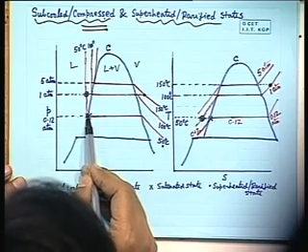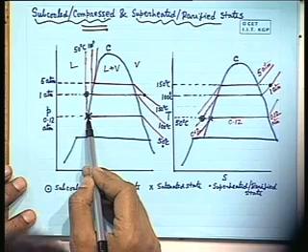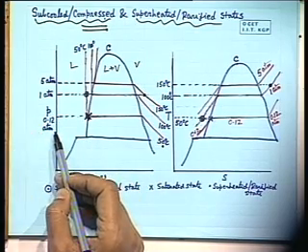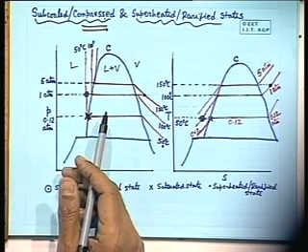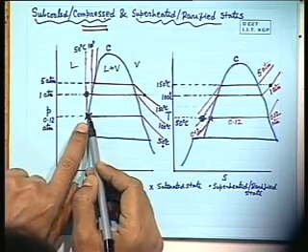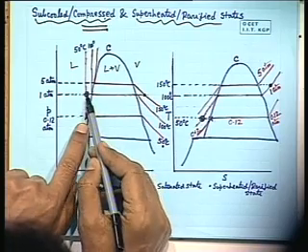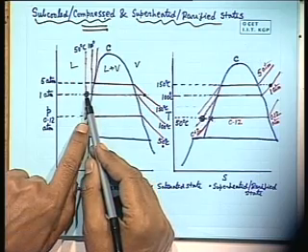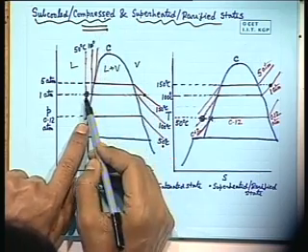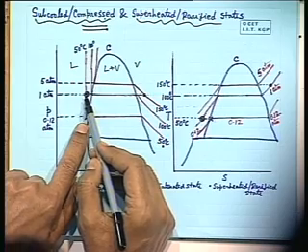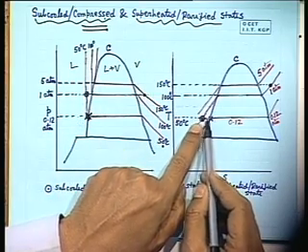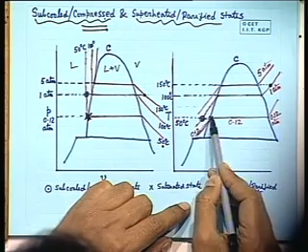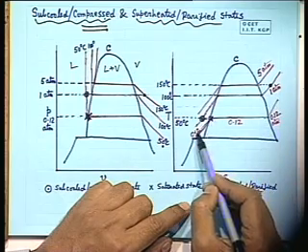So if I go on reducing the pressure, there will be a point where 50 degrees Celsius is the saturation temperature, and at that point the pressure is 0.12 atmosphere. This I have taken from the table. That means at 0.12 atmospheric pressure, water boils at 50 degrees Celsius. So you can tell that this point is at a compressed state, that means at a higher pressure than the saturation pressure corresponding to its existing temperature. So from that angle, this point is a compressed state. Clear? Through that point there is a constant pressure curve which is 0.12 atmospheric pressure.